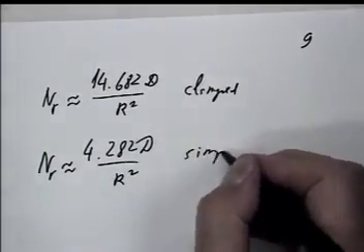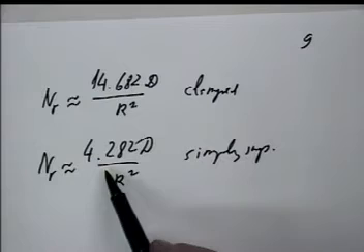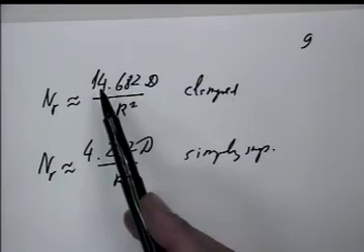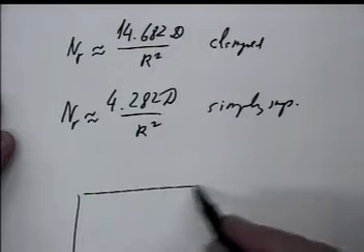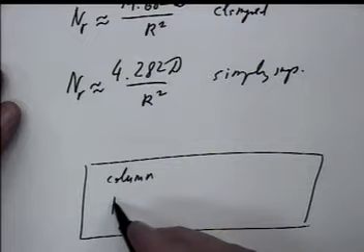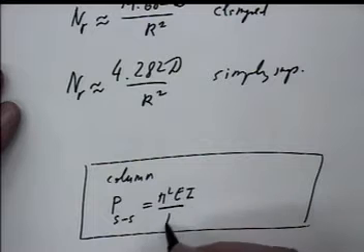So how many times bigger? No one has a calculator? Okay, so it's about 3.5 times bigger, and not 4 times. In order to be 4 times, we had to have more than 16. So in the beam case, if you remember, in the column case, P simply supported equals pi squared EI over L squared.